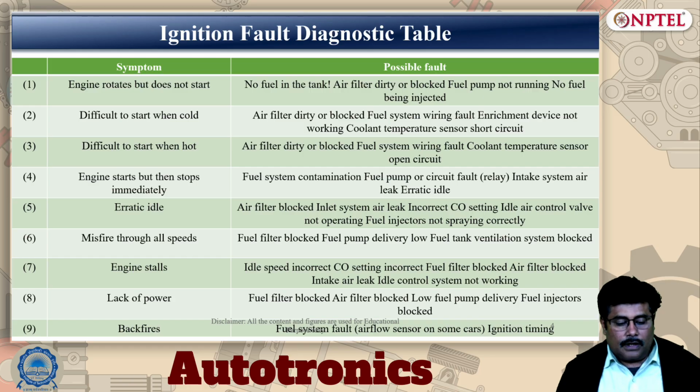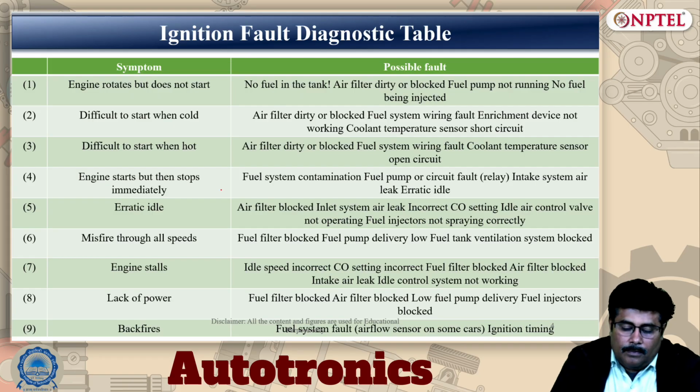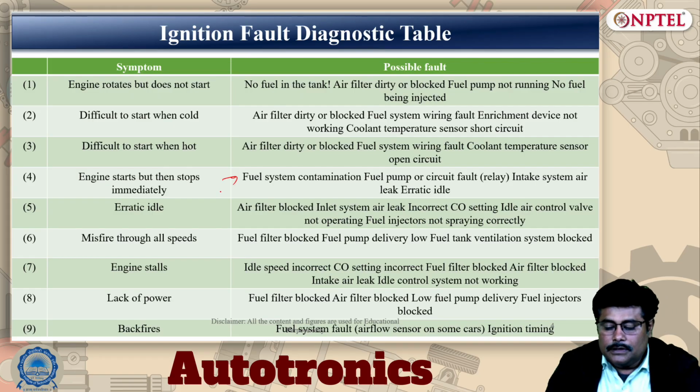One of the key symptoms is that the engine starts but stops immediately. This may be due to fuel system contamination, a fuel pump or circuit fault, the relay, or the intake system, or there might be a leak.